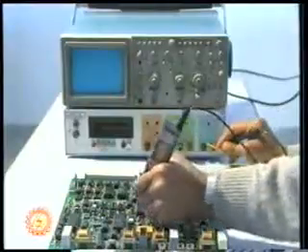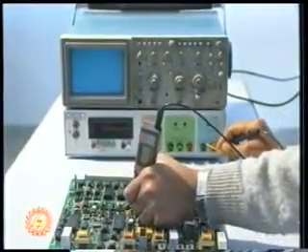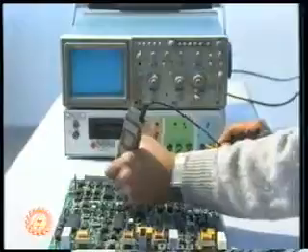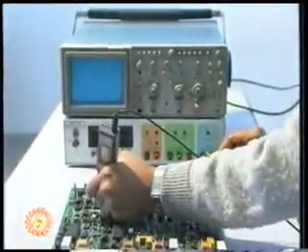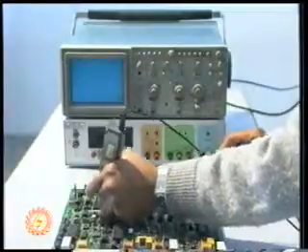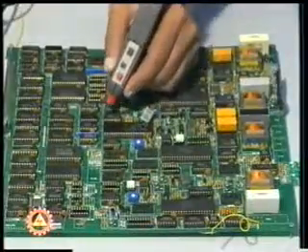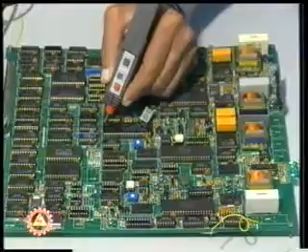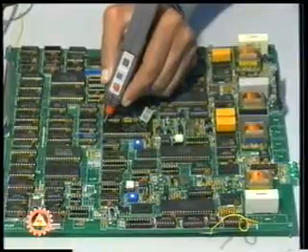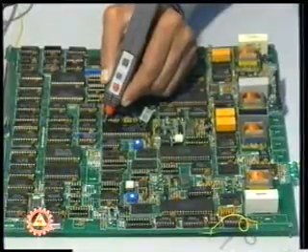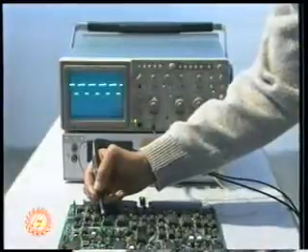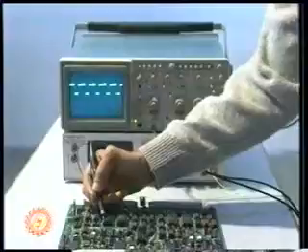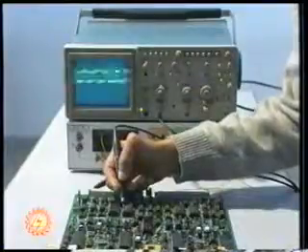We start the testing process by checking all the PCB tracks and find out whether they are properly connected to all correct IC pins. Once the processor starts executing the code, we can verify power supply on each chip, the ground voltage on each chip, the chip select signals on read-write and read-only chips, the read-write control signals on each chip.